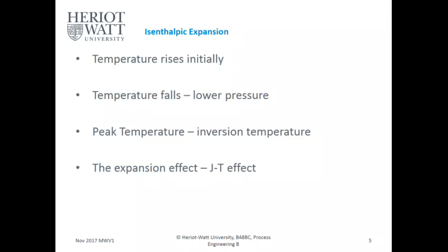This is probably one of the most important things you'll study. If you ever want to go into the oil and gas industry, the Joule-Thomson effect is the most important thing you'll study. For example, if you have these major pipelines with a valve, and the pressure drops after this valve, all of a sudden you have cooling in that pipe. What do you think happens? For example, if you have a gas with a bit of water, have you ever heard of gas hydrates? Hands up, gas hydrates. Anyone?